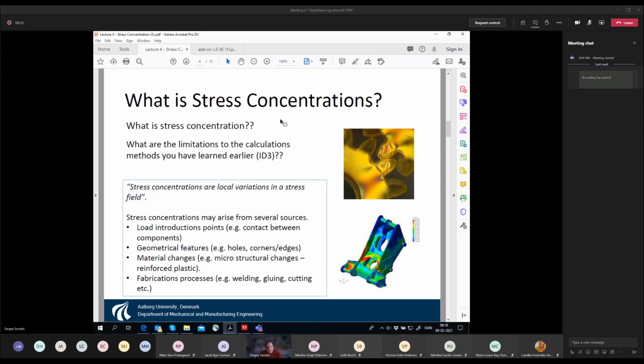if you have micro-inhomogeneous materials, also due to fabrication, let's say welding or gluing, then whatever spoiler you put into the structure, and it's absolutely inevitable, you just can't avoid it, then you immediately have a jump in the stresses.